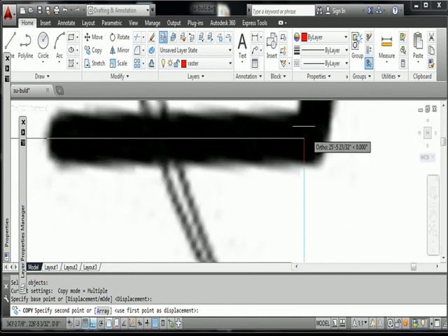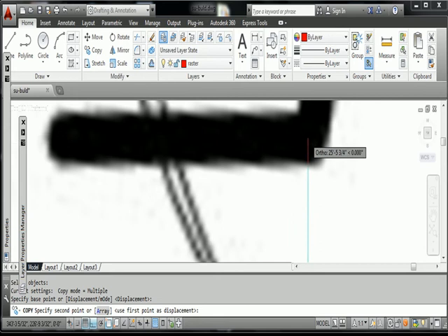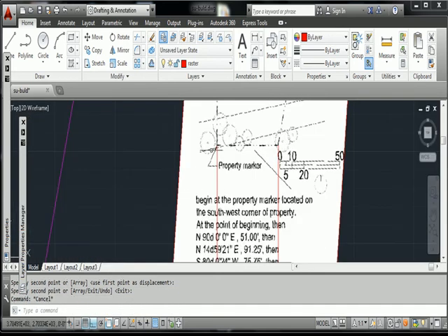And then right about the middle of that point there, diagonally in the middle, is what I'm going to assume to be the 51 feet. The distance between that is supposed to be 51 feet. What is that distance right now? It says 25 feet 5 and 23/32 inches. So what I need to do is scale this drawing so that this line right here can be 51 feet.